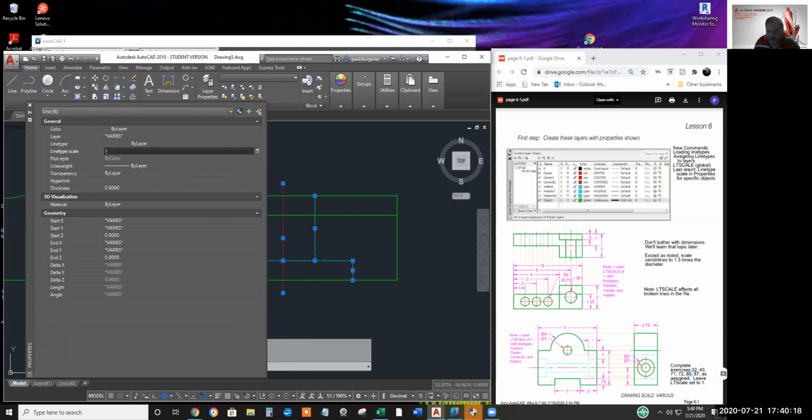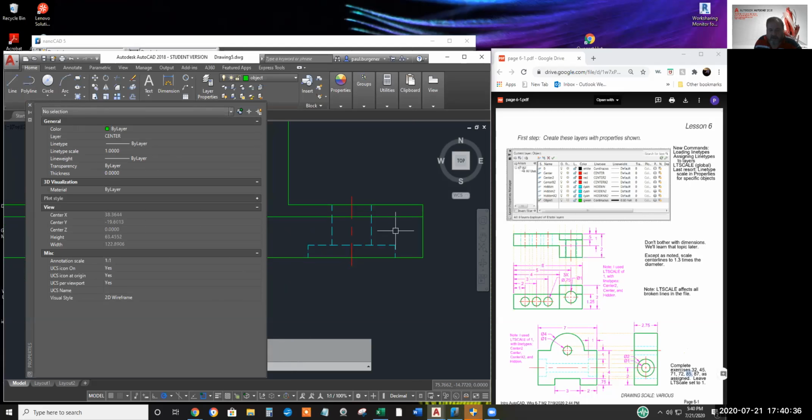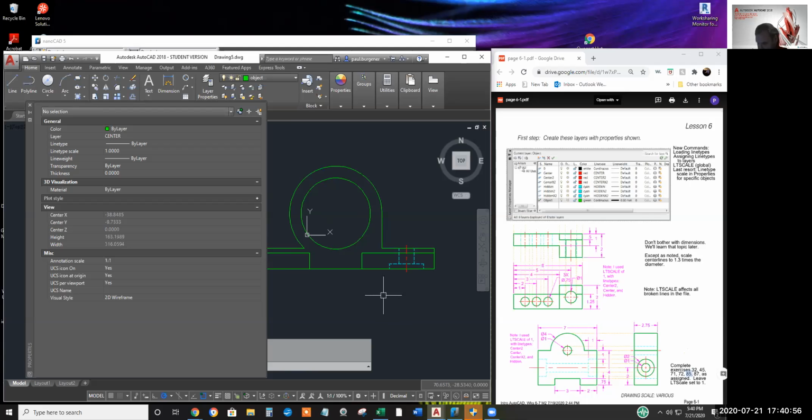I'm guessing 10. Enter. Yep, gambled and lost. Those blank spaces look a little high. Let's change it down to say 8. Enter. Oh, that does everything. Okay, I got a single line in the middle of the 1.3 scaled center line. Kind of cringe when I see a hidden line with just 2 segments in it. That probably matches the textbook.